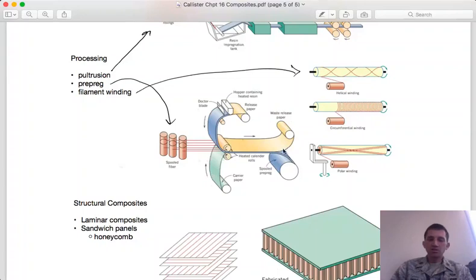You essentially have layers of this material that you can orient and layer together to create your part. You lay them into a mold, typically put a vacuum bag on, and throw the whole thing in an autoclave. The mold shapes the part and it cures in place.